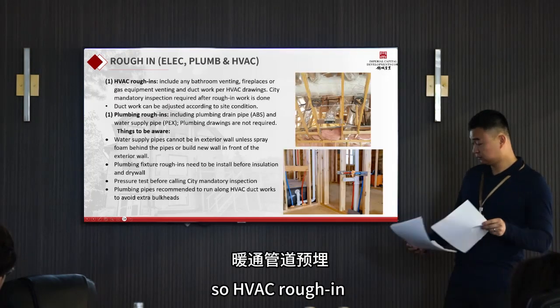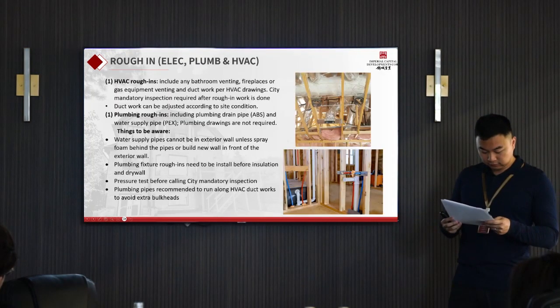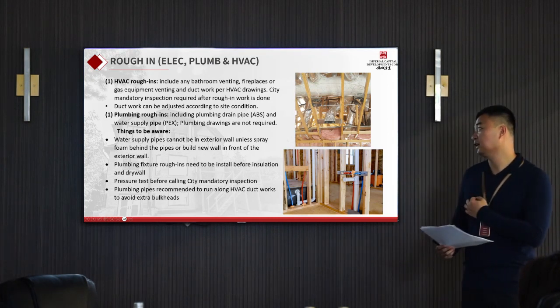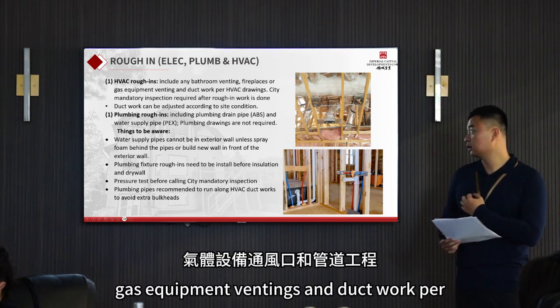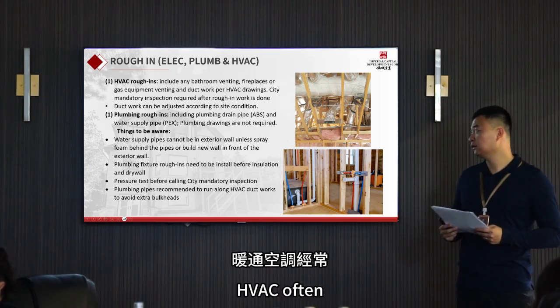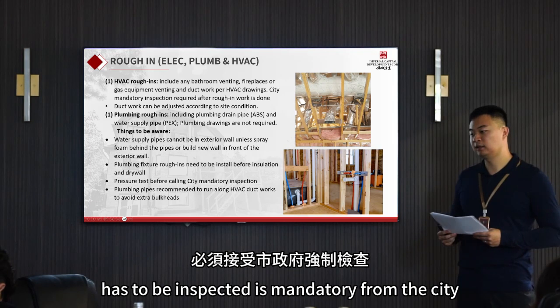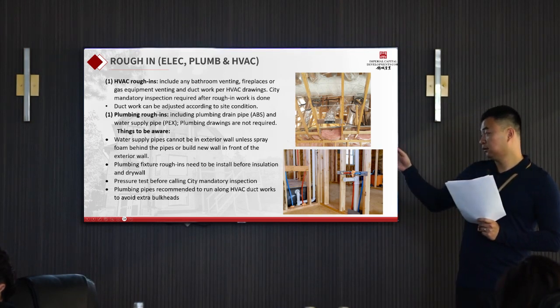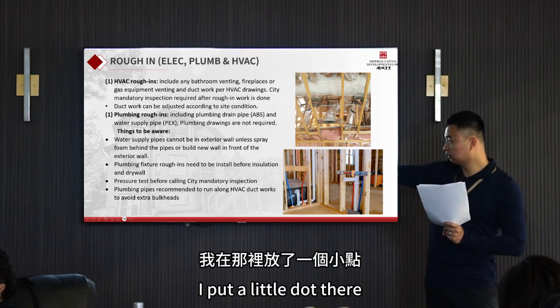So HVAC roughing. It includes any bathroom venting, fireplaces, gas equipment venting, and ductwork per the HVAC drawing. And HVAC roughing has to be inspected. It's mandatory for the city. And things to be aware. I only put a little dot there.